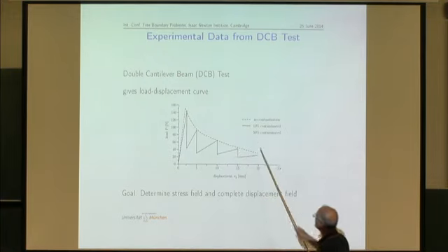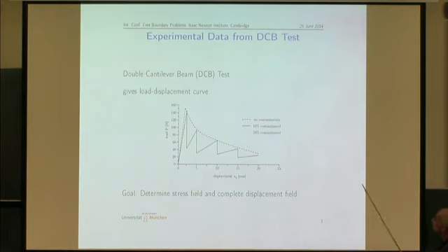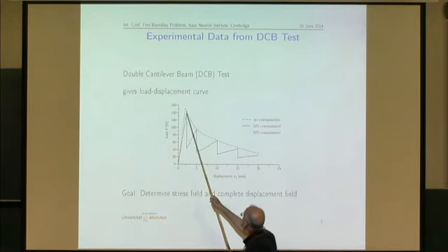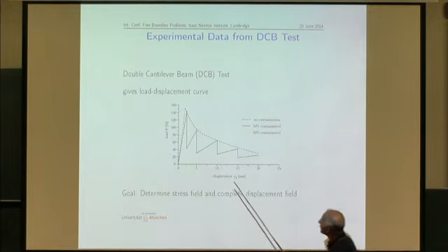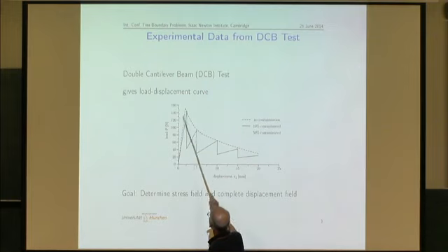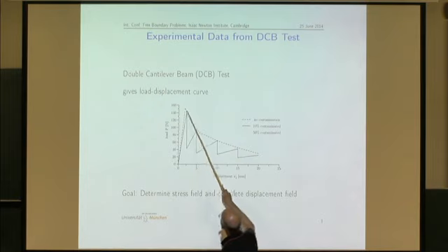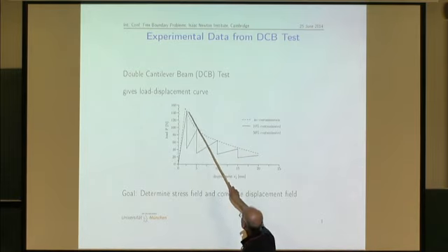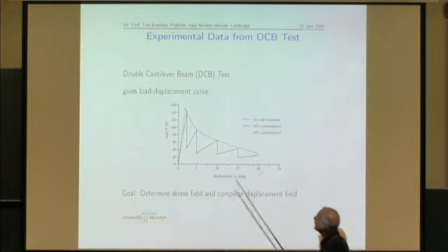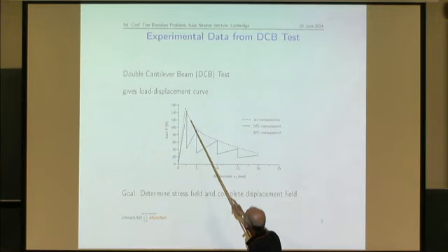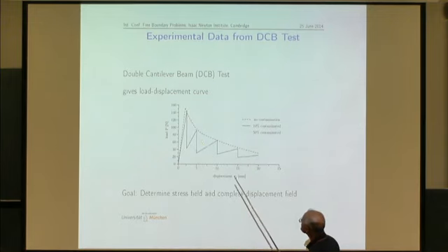But this is not realistic, because you always have some sort of contamination inside. And so what you get, you observe such jumps, such kinks here. What's going on? After elastic load, going up to 150, a critical load of 150 Newton, the crack opens, and because of the crack, you observe an increase of the compliance.